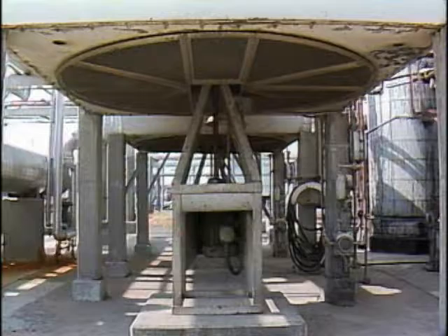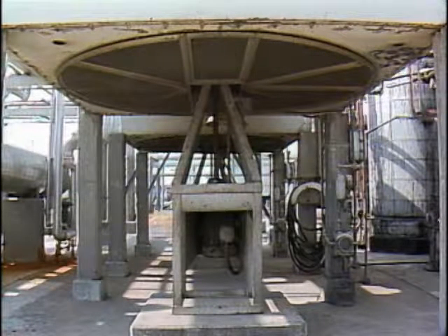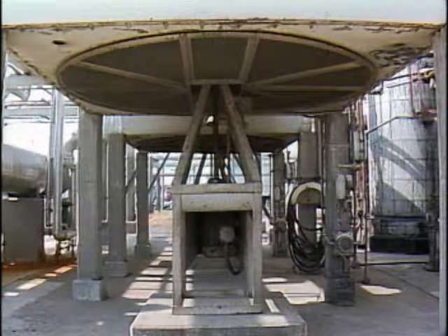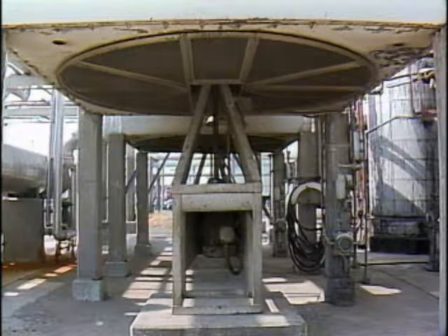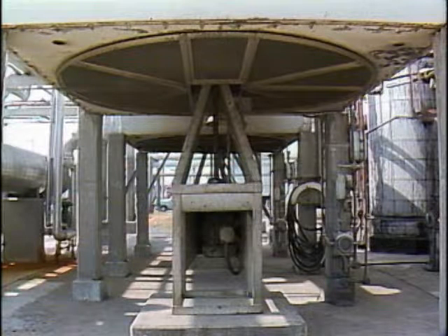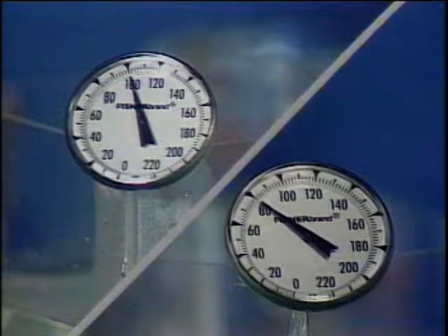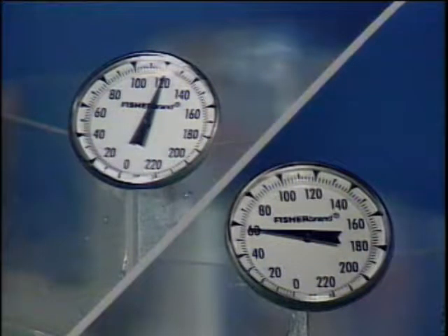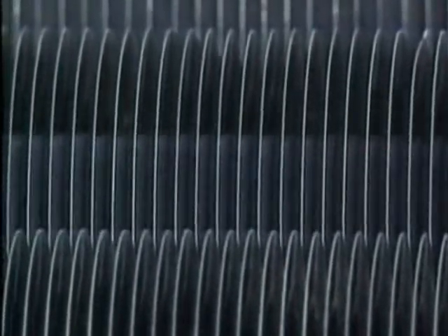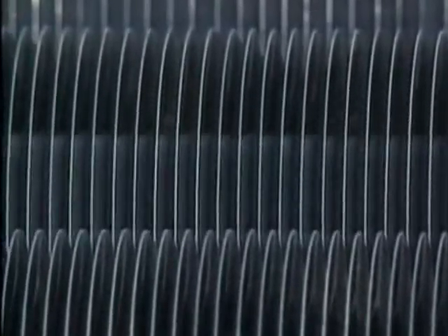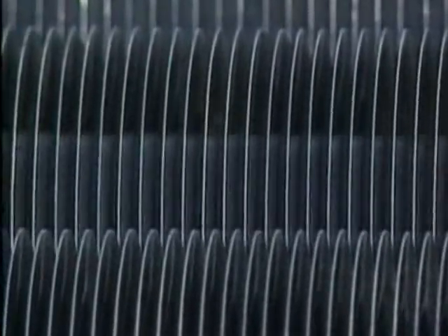To increase the amount of heat transfer to the air, the fans in the cooler can be started. This increases the airflow through the cooler, which increases the amount of heat that is transferred by convection to the surrounding air. For example, as the difference in temperature between the two fluids in a heat exchanger increases, the amount of heat that can be transferred also increases. The amount of surface area in a heat exchanger is another factor that affects heat transfer. Basically, the greater the surface area, the greater the amount of heat transfer that can occur.